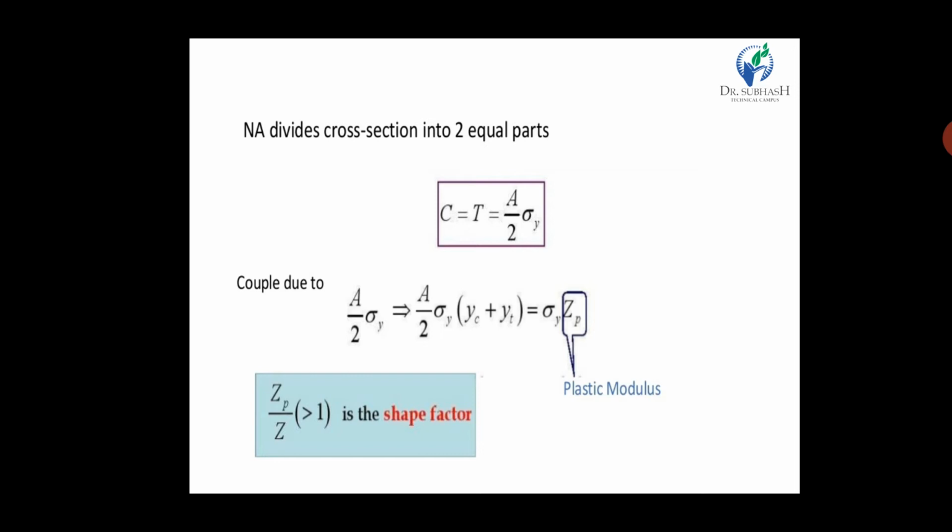Now, what is the advantage of plastic design? It saves material over the elastic method, resulting in a lighter structure. The design moment can be calculated rapidly. It gives an idea about the types of collapse and the strength of the structure. There is no effect due to change in temperature, support settlement, imperfection, etc. The design is very popular for beams and especially for portal frames.